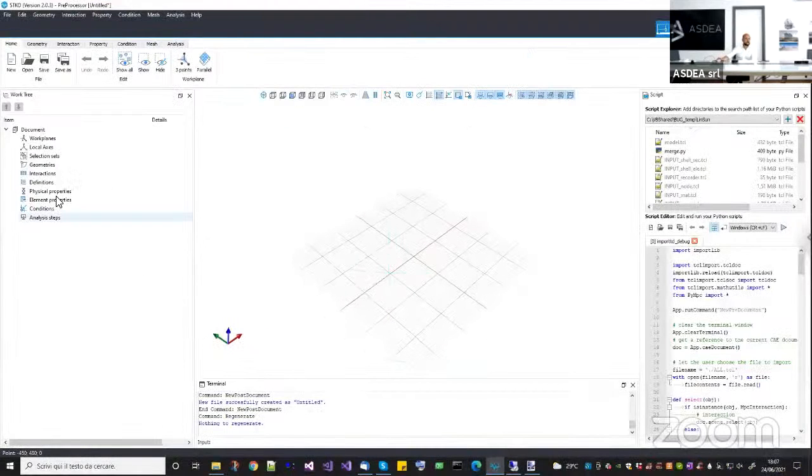Let me first show you where the new element is. It is an element inside OpenSees, but in STKO, it is a boundary condition. Why? Because what I wanted to achieve is to use a constraint that is able to attach joint geometries, not like an equal DOF or a rigid link, because they have some limitation. I want to make sure that, for example, if a node falls inside an element, that node will move as the average motion of the element, which is not feasible with a rigid link, because the rigid link will make the entire element rigid, completely like a rigid body.